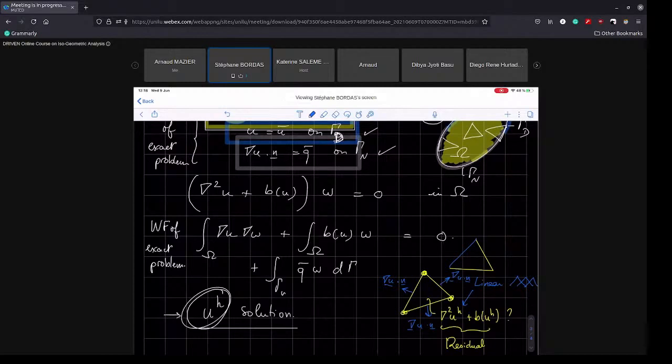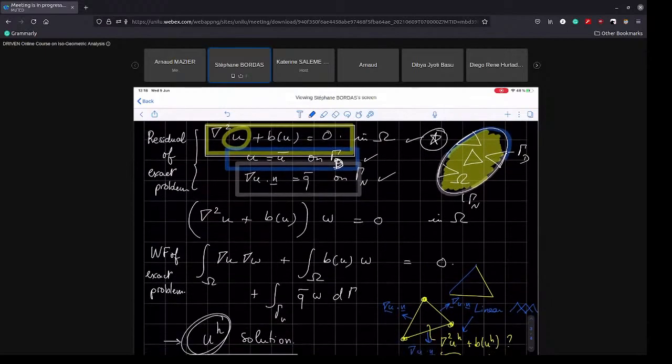So the principle is you measure how well you satisfy the equation that you solved at the beginning. So in your question before, you said, okay, how do I know where to put the control points and how many control points to put down? Well, the answer is, I don't know, because it depends on the problem you solve, first of all. But a way to answer the question is to use an error estimate. And if you use an error estimate, you will be able to really make a sound decision as to yes or no, should I refine, and by how much.